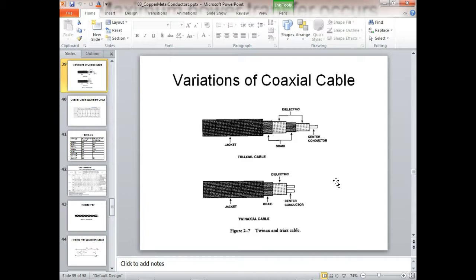DeviceNet uses this type of coax cable too, because it really helps us keep out a lot of electromagnetic interference. These are rated around 100 megahertz, and it's hard for us to understand how you can put 200 channels and all of them share it at the same time. But what we do is we ride them on a carrier, and as long as the carrier's within the range, then it'll pass it okay.